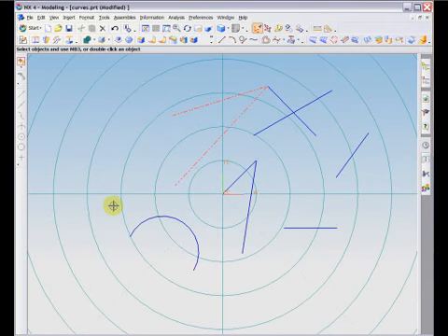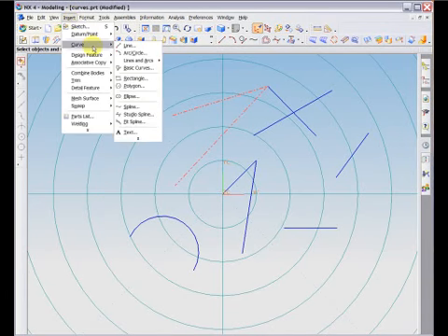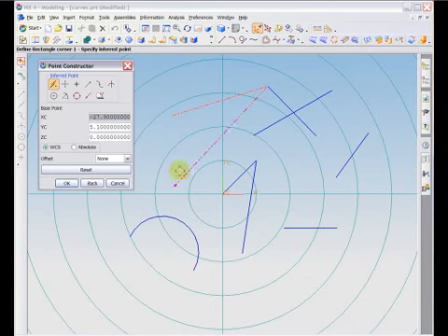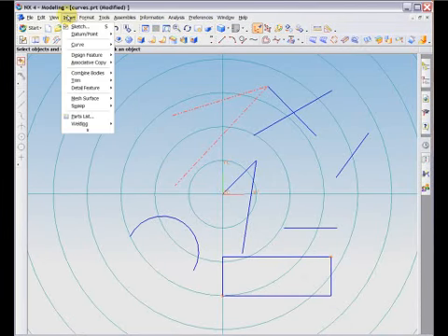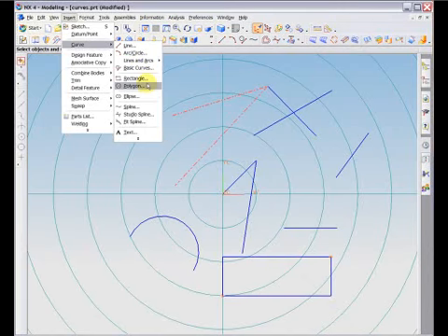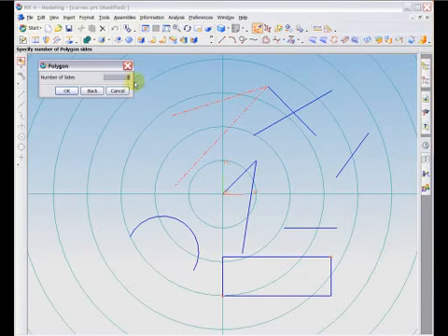Finally, there are just a few more options in the Insert Curve menu to note. The rectangle dialog box is much like that of basic curves. Choosing two opposite corners will completely define your rectangle. You can also make regular polygons through the Insert Curve command. Simply choose the number of sides you wish, then specify an option for defining its size.